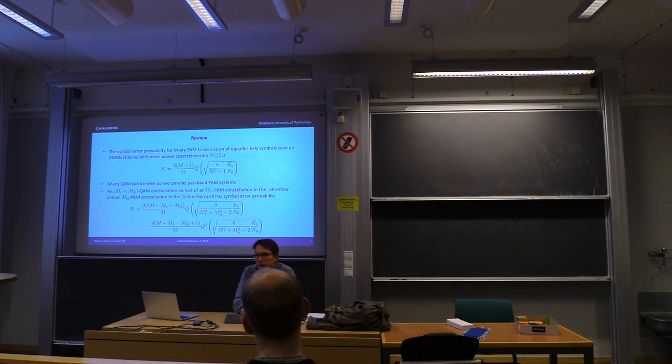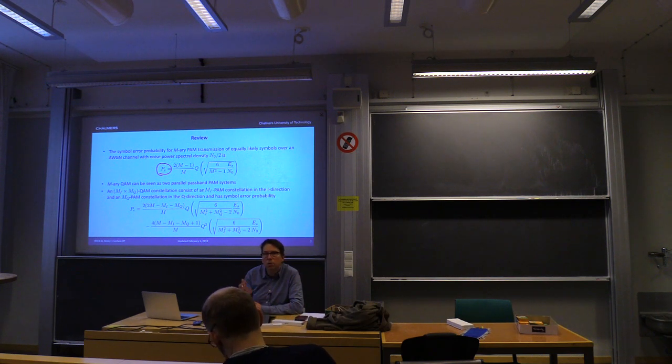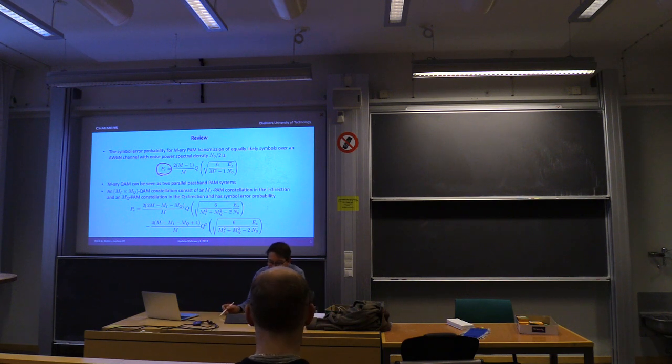The transmitted data is random. We arrived at the error probability for pulse amplitude modulation, M-ary PAM, where we have Gaussian noise with the power spectral density N0/2, and then we have this expression. We will interpret this in graphical form a little bit later today.